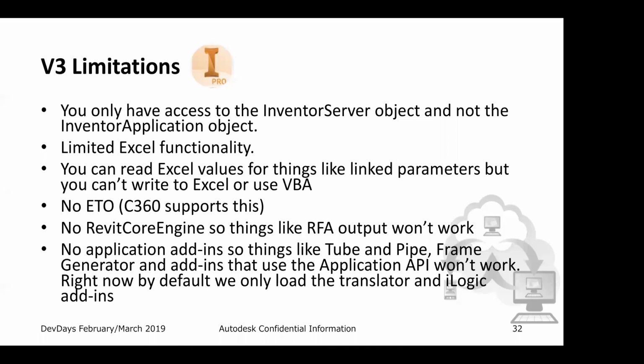And in some cases, you want to use Inventor to create families using the Revit Core Engine, but this is not available yet. That's why in the other sample, we converted from IPT to SAT and not to RFA, which is something that is supported locally. We don't have the add-ins that are inside Inventor, like those listed here, and of course the iLogic add-ins as well.